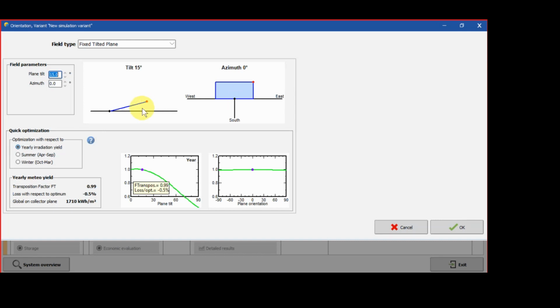So for those in the meeting room here, this is the example. Let's say the front here is north and that is south. So this is your module. The module will be tilted 15 degrees, and the surface of the module will be pointed to the south. The advantage of this kind of configuration is that we know the sunrise and sunset is from east to west. So north, south, east, west. So throughout the day, we can obtain the maximum amount of sunshine on this module.